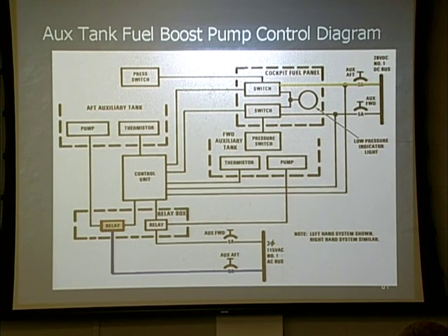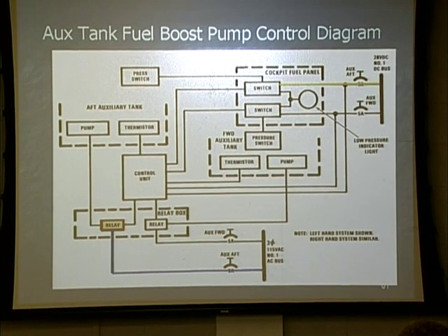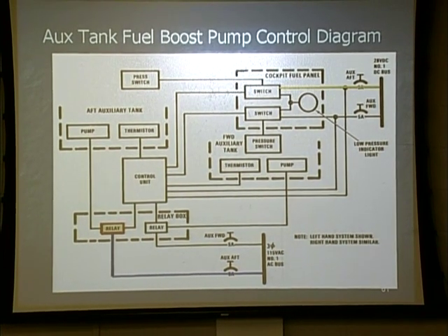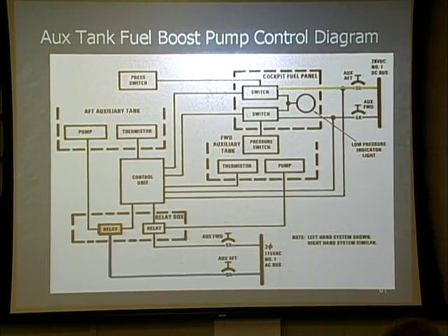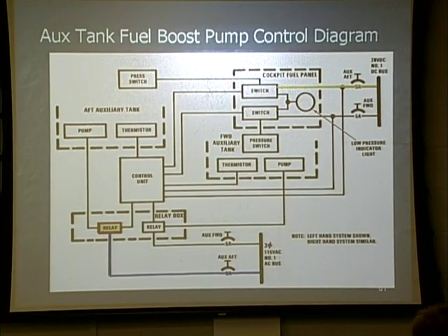Again, DC controlled, AC operated. Just reinforcing the fact of what? If I lose a DC system, I'm still going to lose the pump. If I lose the AC system, of course I'm going to lose the pump. But a lot of people forget that association, and that's why we're showing you this. This just helps reinforce it.